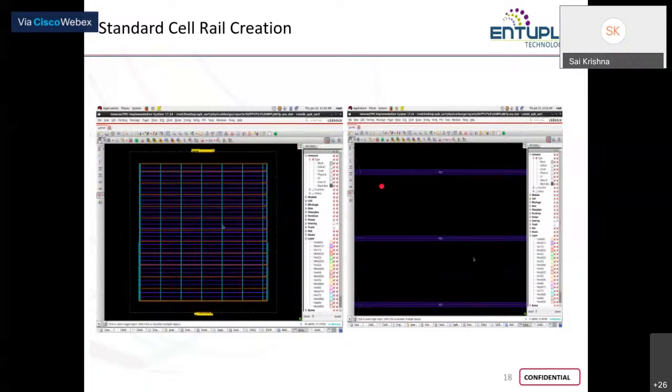We know that fact, but your EDA tools do not understand it. That's why, to the left side and right side boundary, we place certain dummy cells whose job is to block any standard cell that tries to move outside the core boundary.